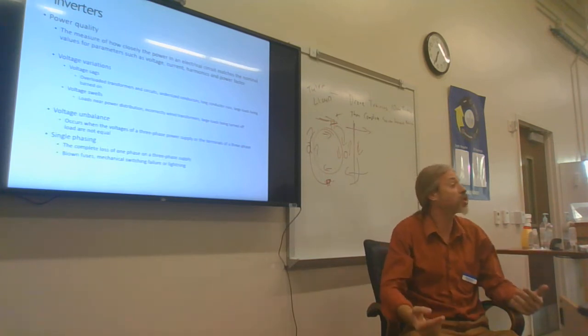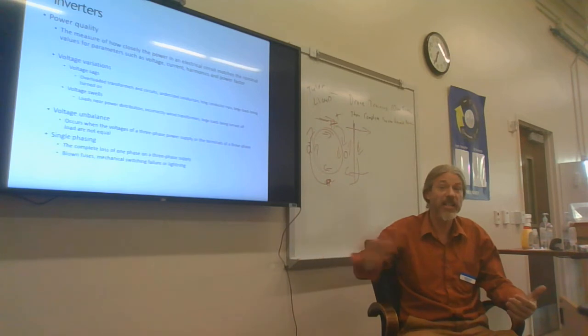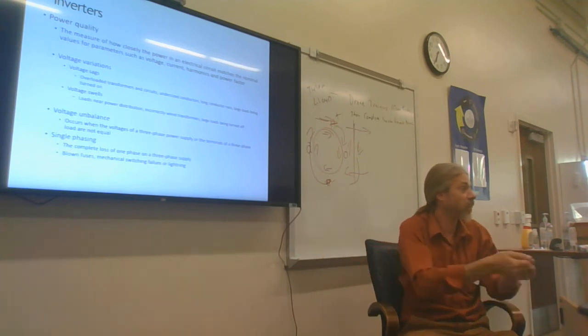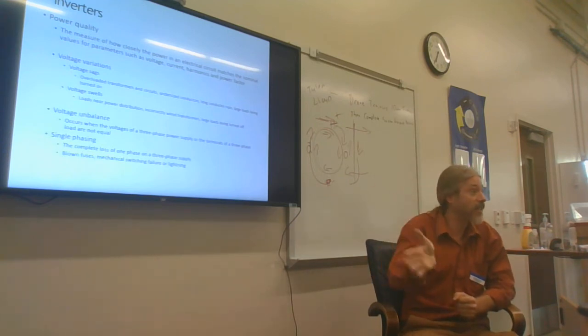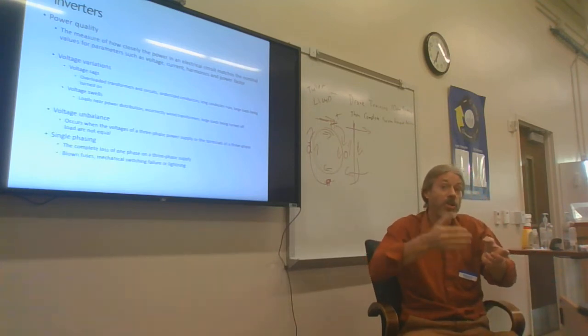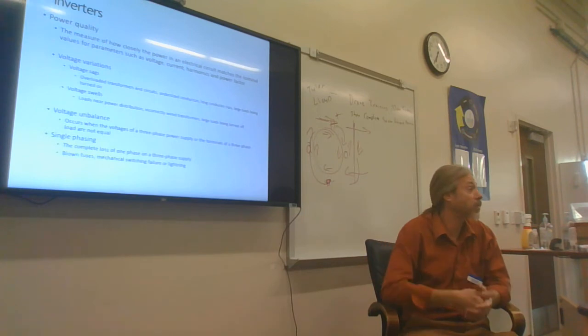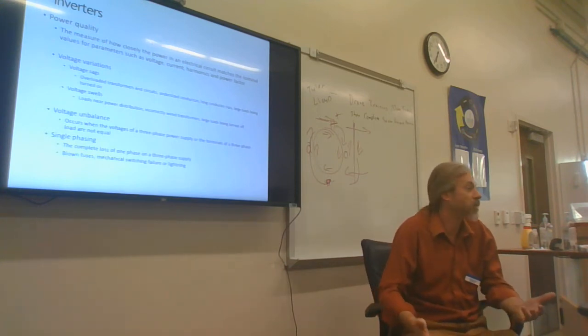Sometimes it's called ghost voltages. Like, hey, this line, this wire isn't connected to anything, yet I've got 4 volts of power in it. Why? Because there is an existing line that has AC power running in the same conduit, and every time it comes on, off, on, off, on, off, it is creating or inducing a voltage in the other conductors that are in that conduit. That's part of the reason that there's maximum fill rates for conduits.